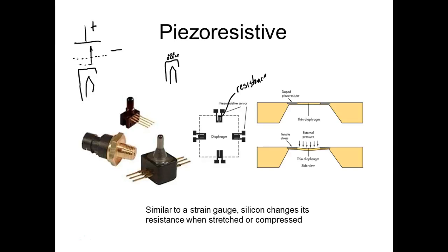So our most popular pressure sensors out now are probably going to be solid state. And they use semiconductors. Oh, they could use strain gauges too, but most of them use semiconductors. Notice they're mounted different ways. And they average them to one.